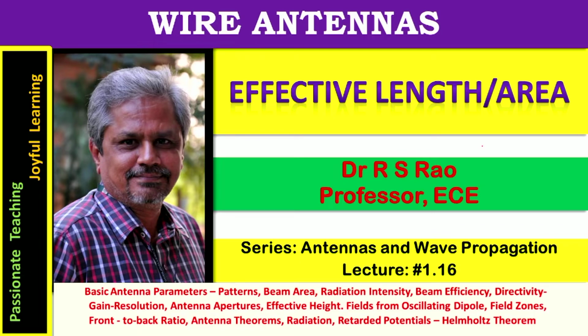One is effective length. This parameter is more relevant to wire antennas. It is useful to describe the antenna both in transmitting mode as well as receiving mode. Another important parameter we consider here is effective area. It is more relevant to aperture antennas. It describes the performance of the antenna while it is functioning in receiving mode.